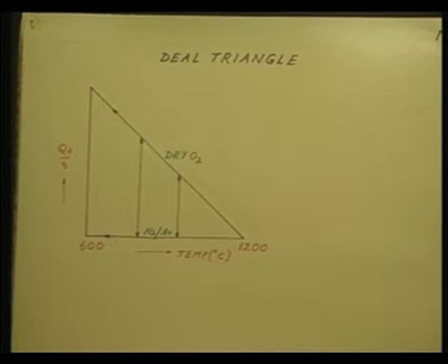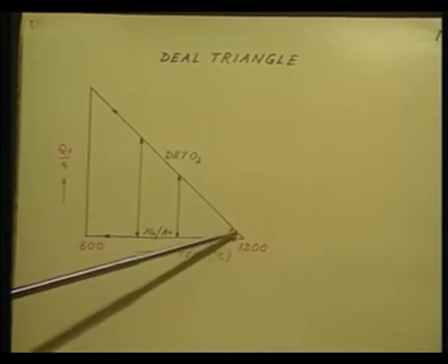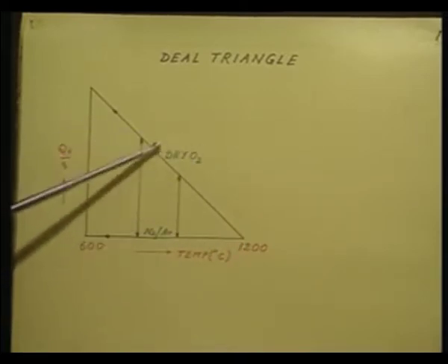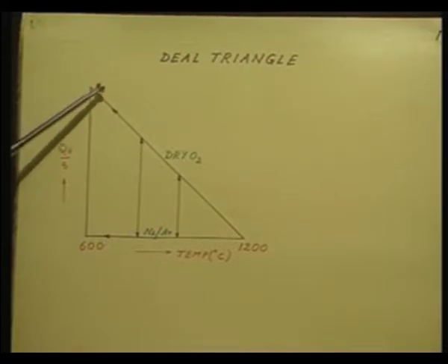Now, let us say that the oxidation is taking place at a very high temperature, 1200 degree centigrade, and now from this temperature the sample temperature is being lowered, and while reducing the temperature, still an oxidizing ambient is being maintained. Therefore, there is the possibility of having incomplete oxidation. So, this is the path it traces. As you reduce the temperature, if it is done in dry oxygen ambient, this is the amount of fixed oxide charge you get, which is very high, greater than say 10 power 12 per centimeter square.